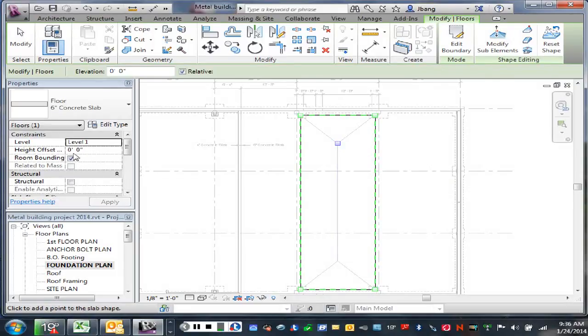and the elevation of this point is going to be level 1, but the height offset from that point is going to be minus, well, we should figure out, do I want a 1/4 inch per foot slope on this or whatever. And so it's about 10 feet in. It should be 10 feet in because it's a 20-foot bay, roughly. So 10 feet in, if I was dropping it a quarter inch per foot, that would be 2.5 inches. Okay. Let's say 2 inches. We're going to drop it 2 inches. Because a quarter inch is really pretty steep. You probably wouldn't go more than an eighth.